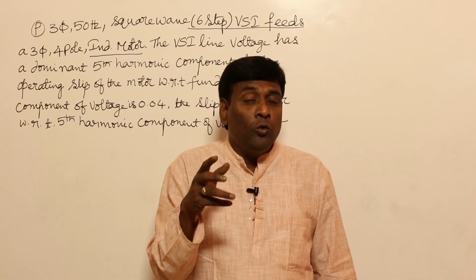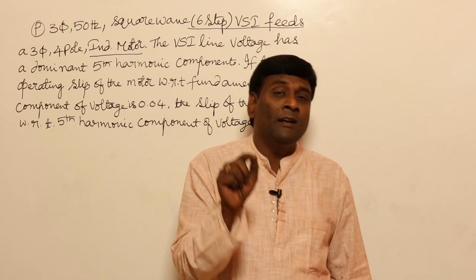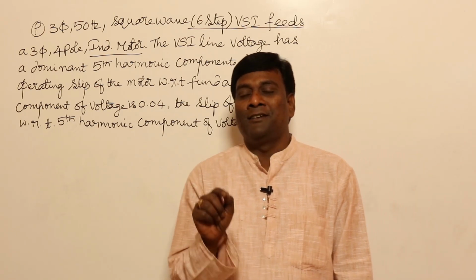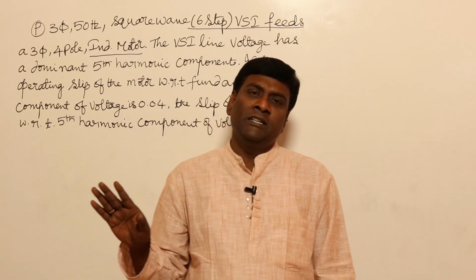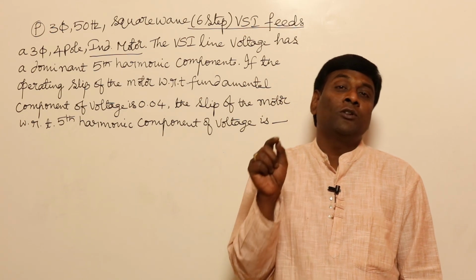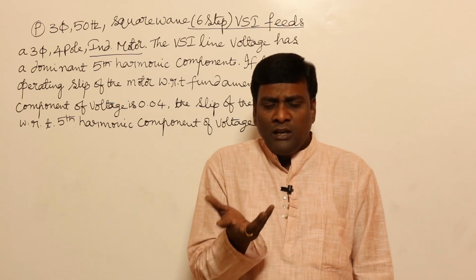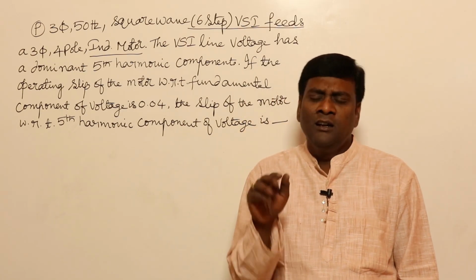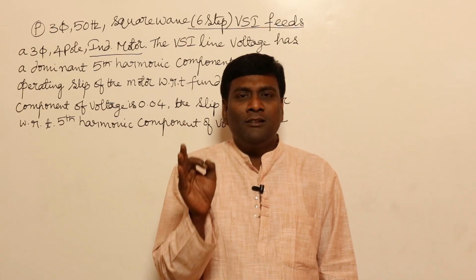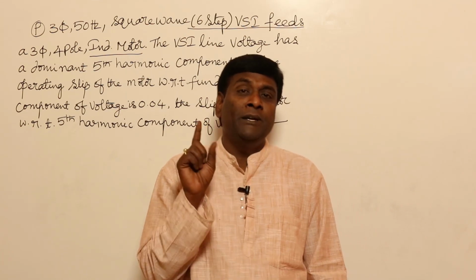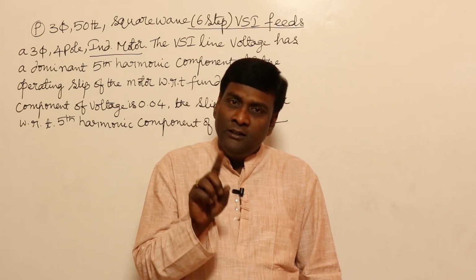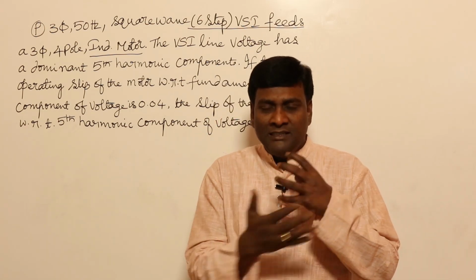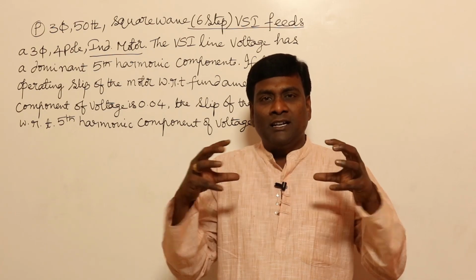So from no load to load, depending upon the speed regulation of the prime mover, should the prime mover speed be reduced or not? Yes. But still, in no other machine do we consider speed regulation of the prime mover, because the prime mover is assumed to have infinite mechanical inertia. In drawing the characteristics of all generators, speed regulation of the prime mover is not considered. For example, this is the generator, this is the prime mover, and these two are connected.